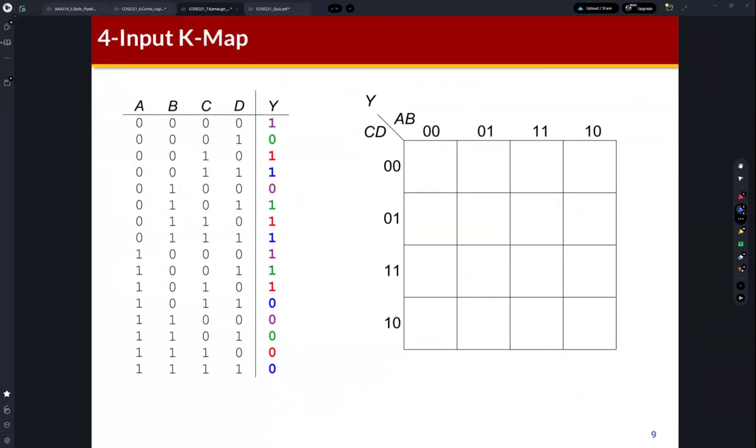So this is the point for the Karnaugh map. Firstly we need to know that the order is 0 0, 0 1, 1 1, and then 1 0. How can you build the Karnaugh map here? We can start from this one. In the truth table, A B is 0 0, so we can first build this column, right?